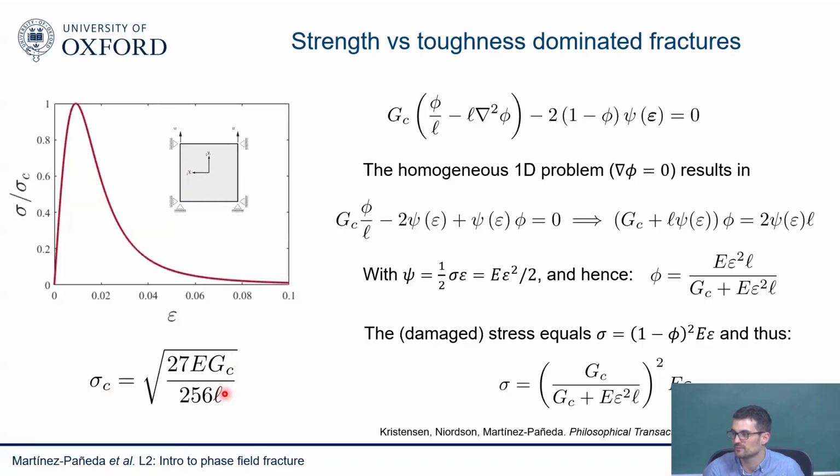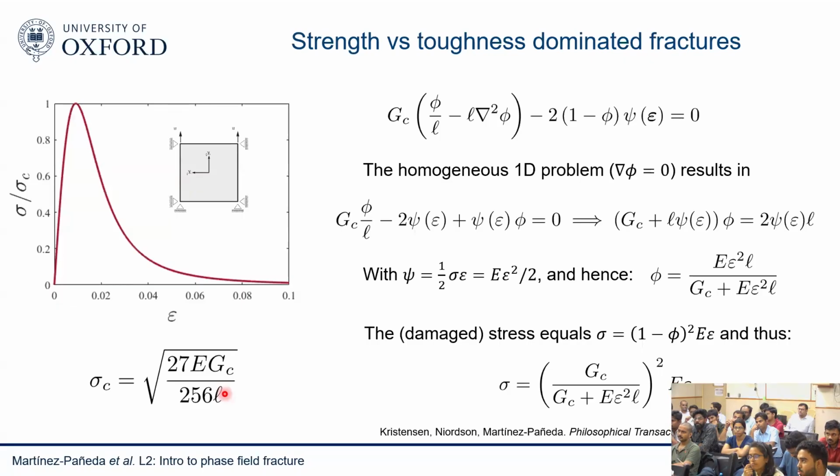Thanks. Usually in ductile materials the fracture process zone is smaller. But if I talk about quasi-brittle material, in this case we have a sizable fracture process zone. So should L then be higher, and can we take some number of elements inside L? Is there any relation between L and element size?